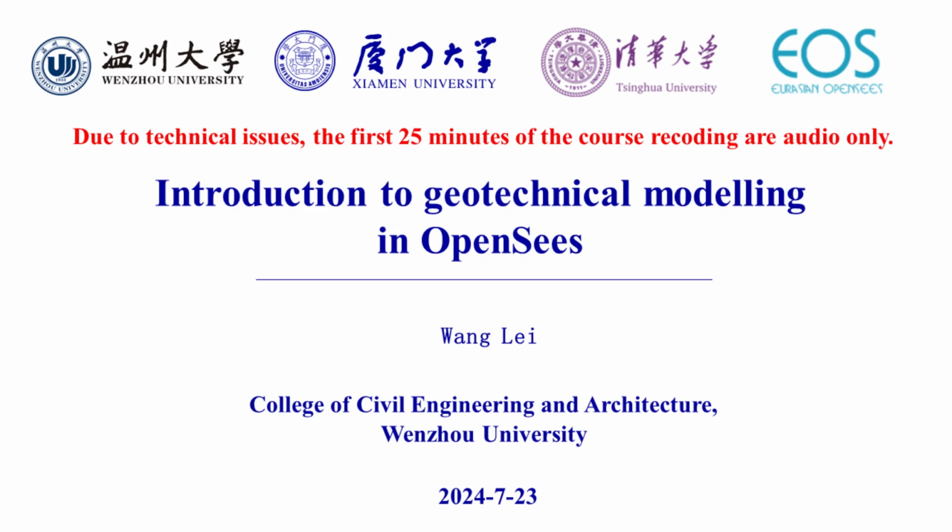And the numbers following the command node indicate the tag of the node, and the coordinates in the x and y directions. And if we want to set the lump mass to the node, we should use the keyword mass here. And the numbers following the keyword mass indicate the mass in the x, y, and rotation directions. Okay, so we can use all these commands to define the nodes of the